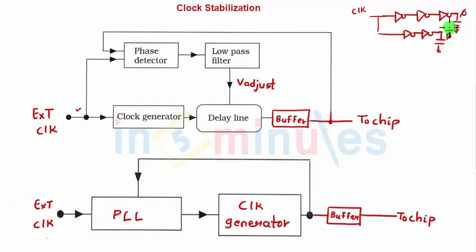So the same thing, my external clock is given to my clock generator circuit that produces the necessary phi and phi bar. Now this in turn is given to a voltage controlled delay line unit. We'll understand what this does. This is a delay line which is controlled by a voltage from a low pass filter. We'll understand quickly what is going to happen. Delay line itself suggests that it will slow down my signal in case the need be. We will see when that happens.